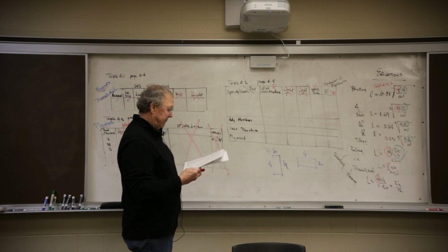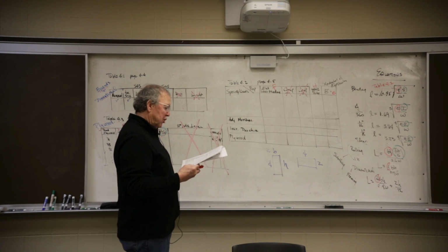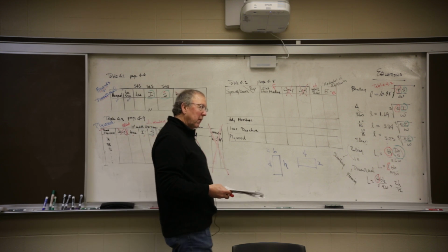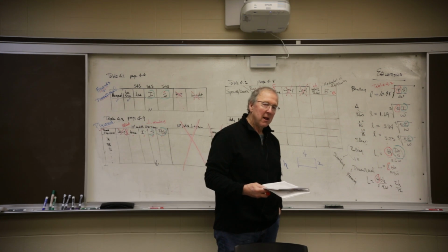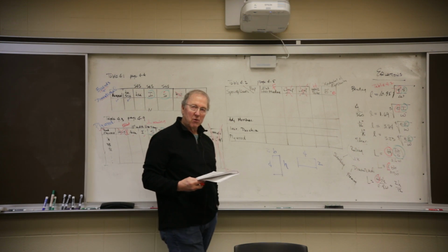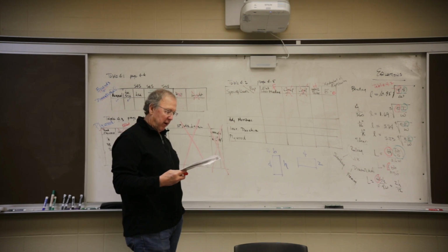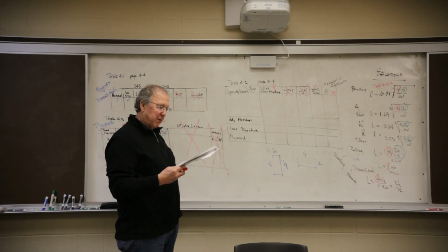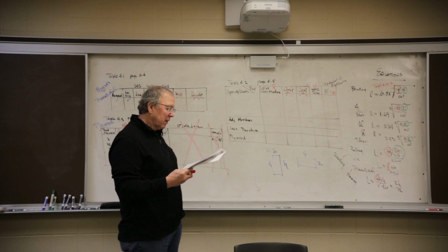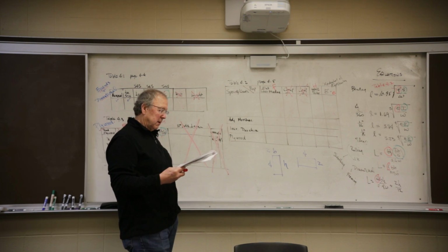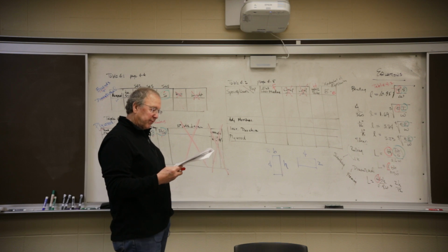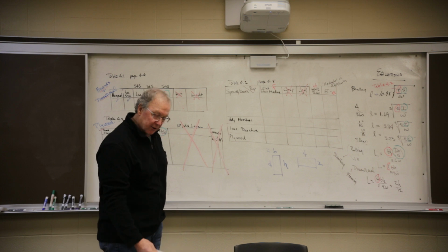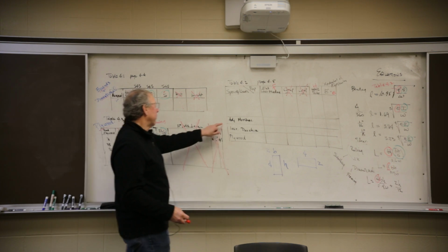Okay, if you go down below this hem fir, adjustment for moisture content. Okay, what happens? The wood gets wet, the allowable stress goes down. So they make adjustments there. If you look at it, you multiply the allowable stress by 0.86 if it happens to be bending, 0.97 for shear, 0.97 for modulus. So this is an area that students have a rough time with.